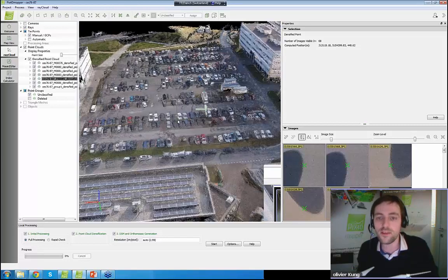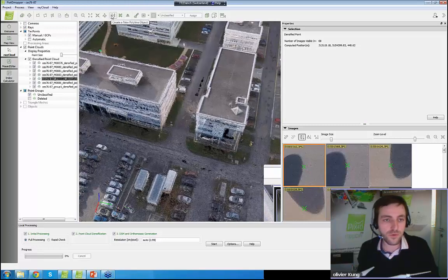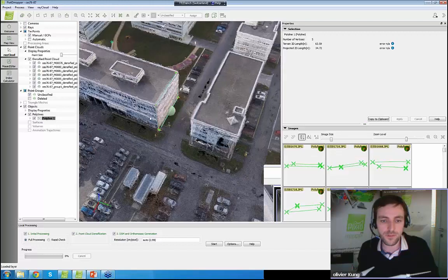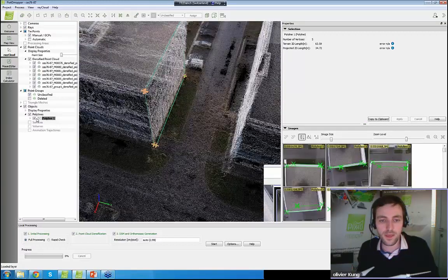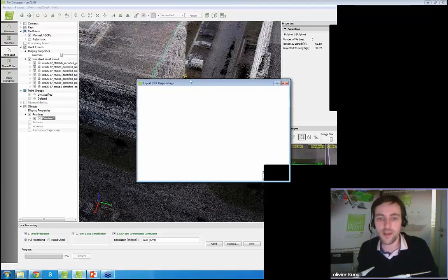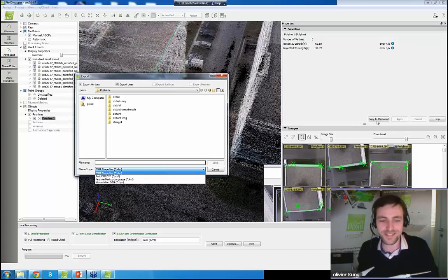Finally, and maybe that's probably the best option, if you want to import not the whole thing but just a few measurements in Autodesk, what you can do is create polylines like this one, which trace the sides of most of the dimensions of the building. And then this line, you can export it as a DXF file that can be easily read in Autodesk.